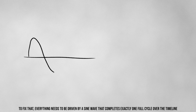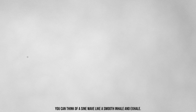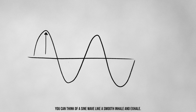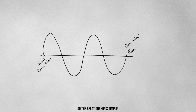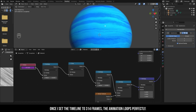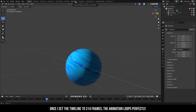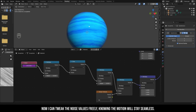To fix that, everything needs to be driven by a sine wave that completes exactly one full cycle over the timeline. You can think of a sine wave like a smooth inhale and exhale. After one full cycle, which is 2 pi radians or about 6.28, it returns to the exact same value. So the relationship is simple. Number of frames multiplied by the speed needs to be equal to 2 pi. In my case, I chose a speed of 0.02. Dividing 6.28 by 0.02 gives me 314 frames. Once I set the timeline to 314 frames, the animation loops perfectly. Now I can tweak the noise values freely, knowing that the motion will stay seamless.